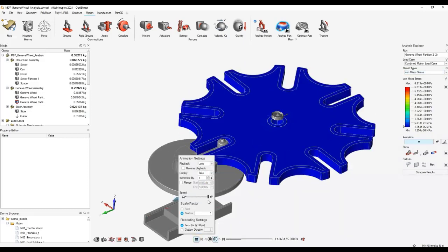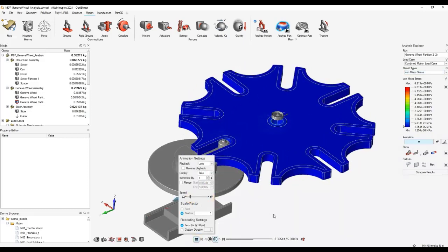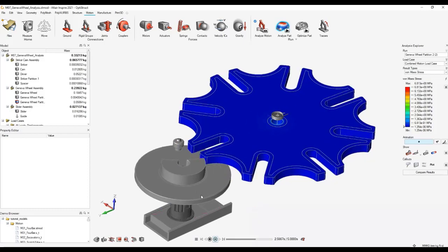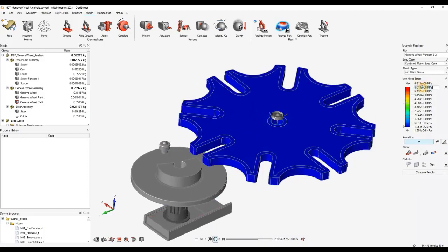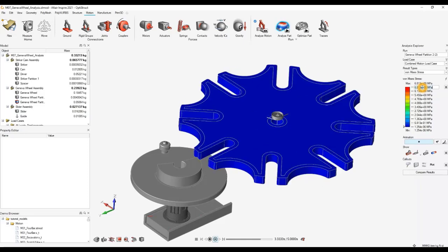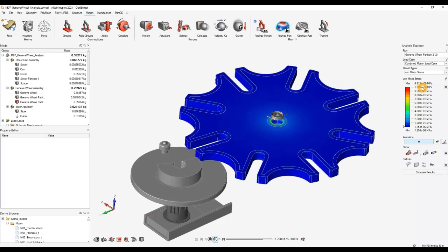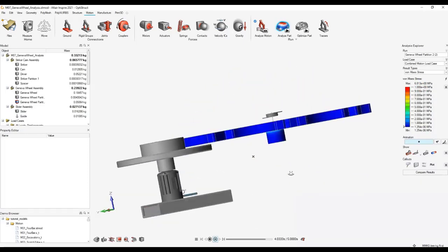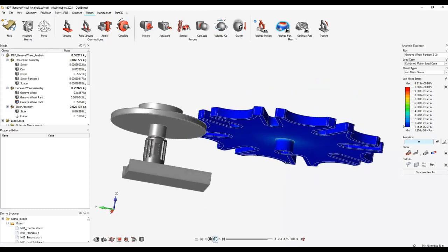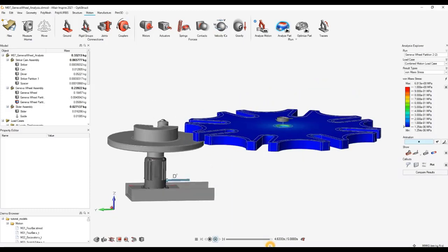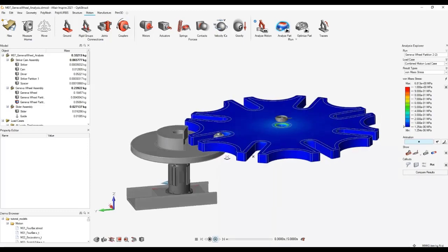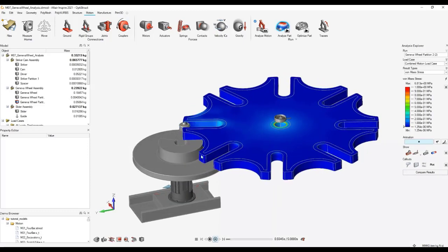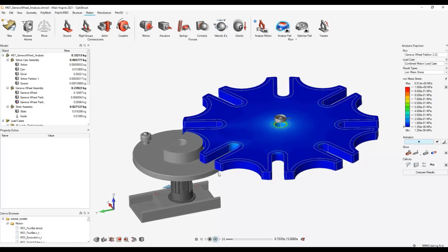And if I were to slow down the speed of our animation a little bit, just to understand it better, we can also change our legends. So let's say if we want to look at anything above 1 megapascal, we can see how our stresses vary in our simulation like this. So we can see every time it pushes it through where the stresses are above 1.